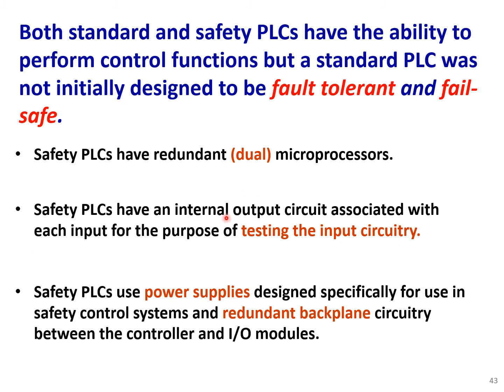Okay, so they have this specific mechanism inside designed to check the performance of inputs, or testing of inputs. Safety PLCs use power supplies designed specifically for use in safety control systems and redundant backplane circuitry between the controller and I/O modules. So you see, they have redundant microprocessors and they have a redundant backplane and power supply.